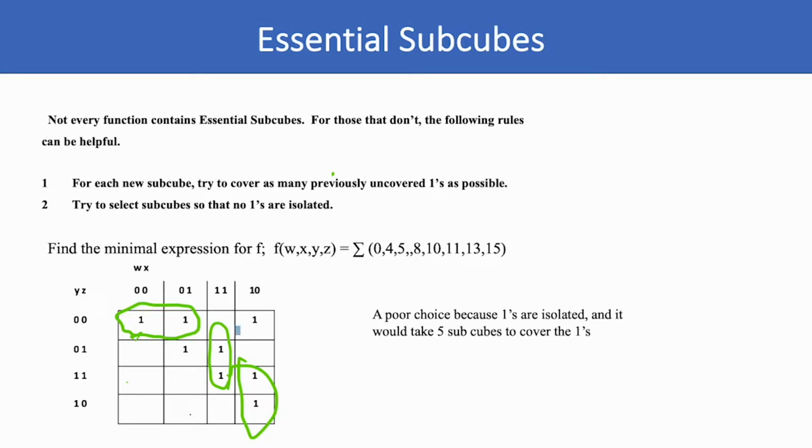More than likely, it'll be something like this, where we have a 1 here and we have a 1 here that we didn't cover. Well, when you're covering ones on a map, you would like to not isolate any ones. In this particular covering that I'm showing here, we've isolated these 2 ones. So this is a poor choice because the only way to cover them now is to cover them with this cube and then this cube right here. And it's a poor choice because we had to use 5 subcubes to cover the ones. 1, 2, 3, 4, 5. And that's because we isolated those 2 ones. Well, let's look at a better way.